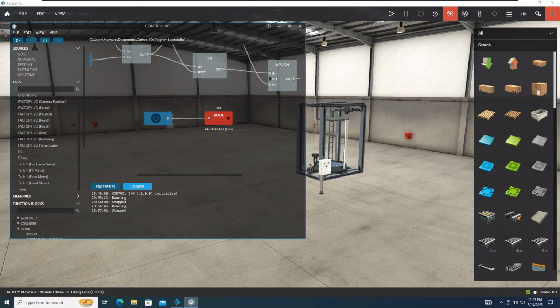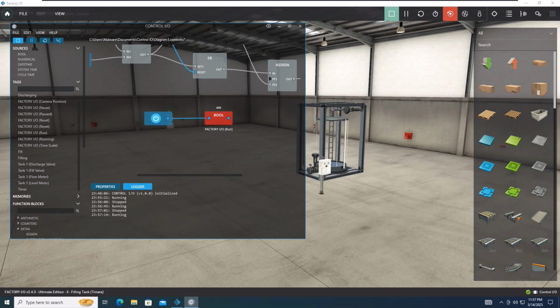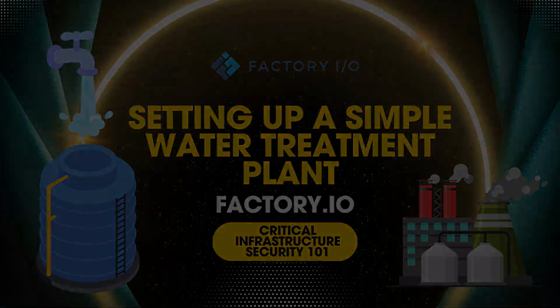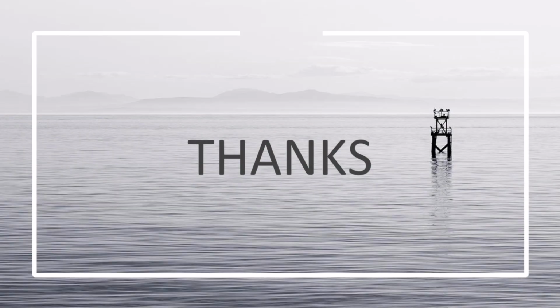So, in this video, we learned how to set up a complete tank filling simulation in Factory I/O. We used analog sensors to measure water levels, logic blocks to automate the filling and draining process, set-reset blocks to maintain the valve states, and a reset switch for manual control. This setup mimics real-world industrial automation, making it a great learning tool for PLC programming.